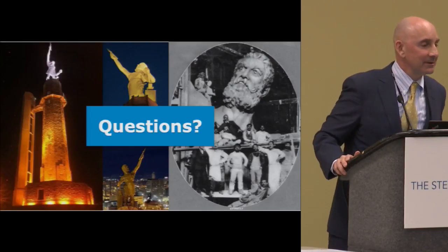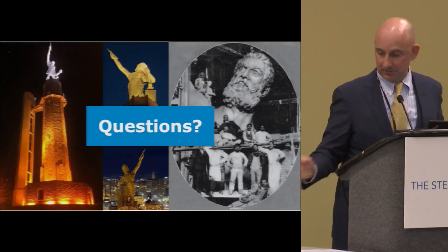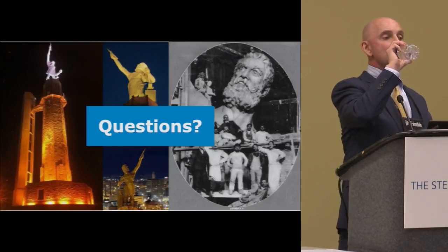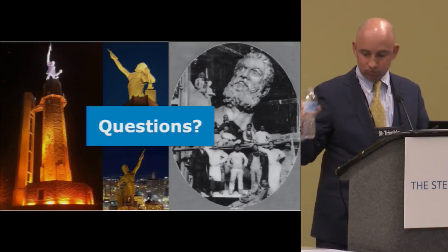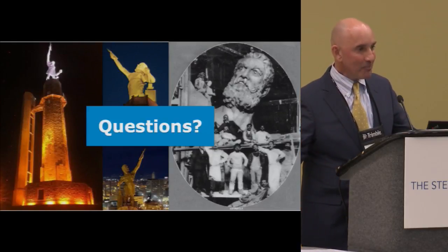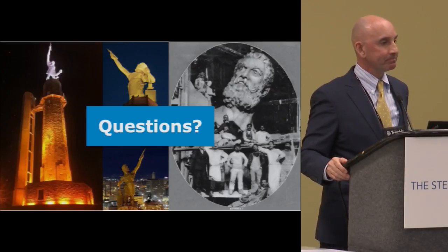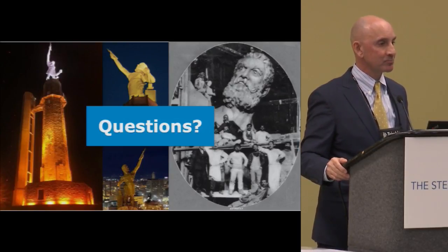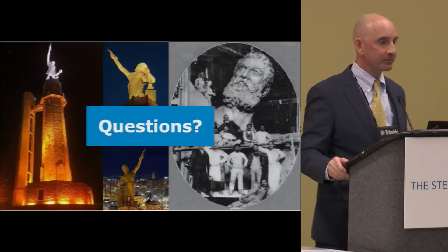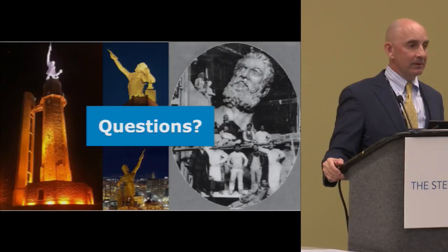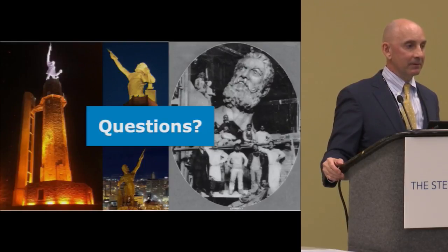Okay, yes. You have a paper that you just put out about plate elements and interaction between shear, flexure, compression, all of that. What's the difference between that kind of interaction and the simple linear interaction on the coped elements here? Because that seems to me like a double cope, especially, it's a plate element compared to just a single plate somewhere.